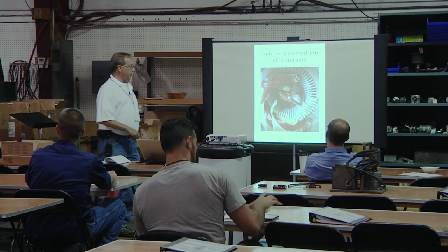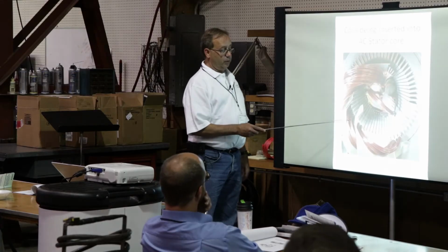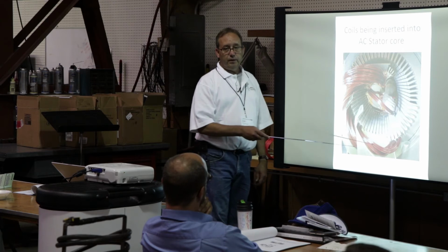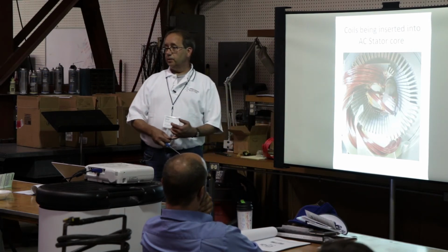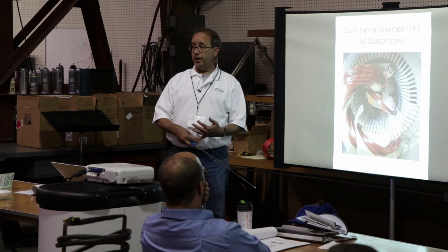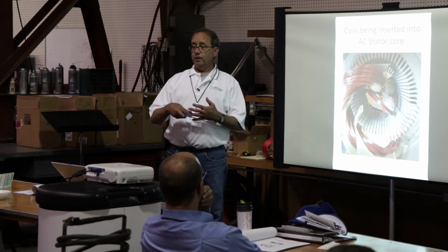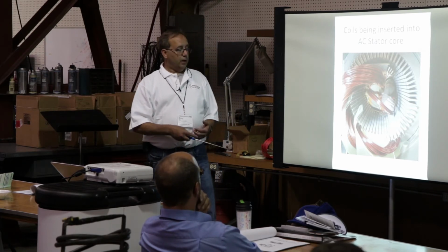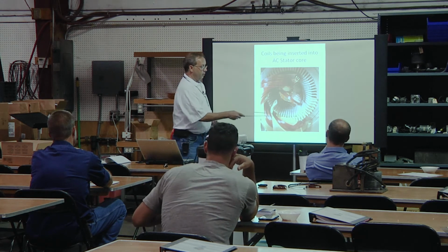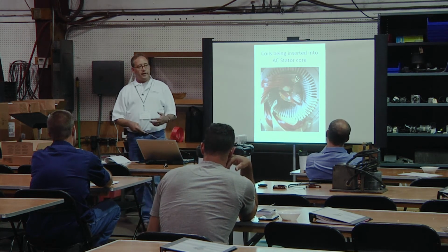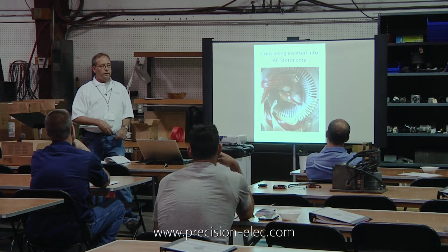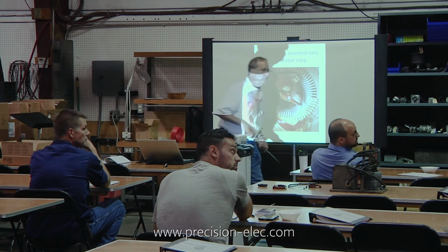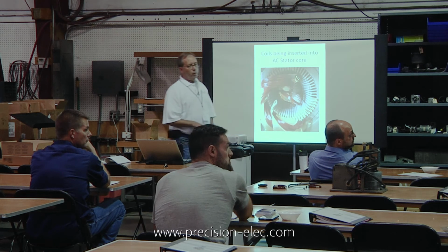In 45 minutes. Okay, these phases are put in, like there's groups. The number of groups is determined by the number of poles. So a 4-pole motor has 4 groups in each phase, right? So times 3 phases, so there's 12 groups total. The number of coils in each group is determined by the number of slots. So we do some arithmetic and we determine, okay, well, we need, like that one there looks like it's got, what, 6 coils per group? It's probably a 4-pole.